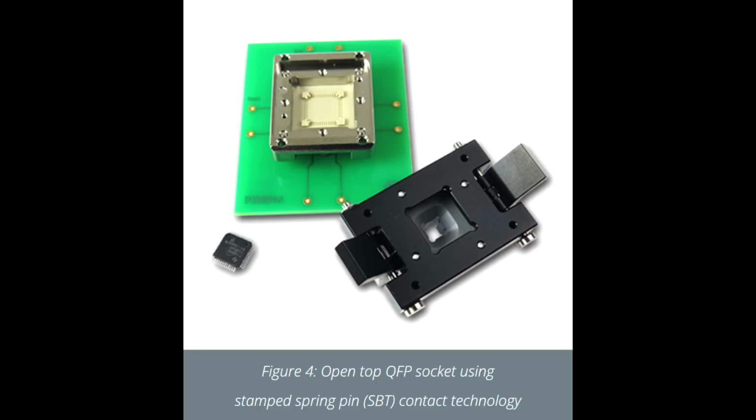If I only wanted to test the BGA, then there are solutions for this that exist already, called BGA sockets. These, I imagine, would not be too expensive, but it just doesn't provide the level of testing that I need. So what I need is an end-to-end test, a system-level test, where I'm putting the chip in an Xbox, and the Xbox tries to use the memory and tells me if it's working or not. I can create a custom BIOS for the Xbox that will test the device as soon as the Xbox is powered on, and it will tell me on the front panel LED if that chip has passed or not.